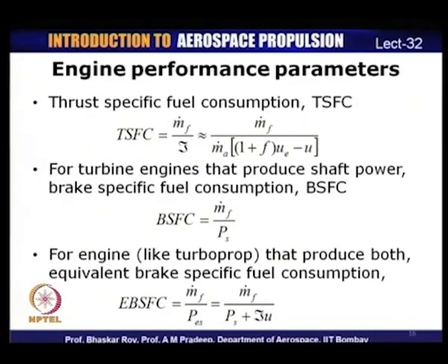So, now that we have discussed different types of efficiencies, let us also look at the other important performance parameter, which is the fuel consumption rate. In the case of air breathing engines, we normally refer to the fuel consumption in the form of what is known as thrust specific fuel consumption, denoted by TSFC. So, TSFC is equal to m dot F divided by the thrust, which is equal to m dot F by m dot A into 1 plus f into (U_E minus U).